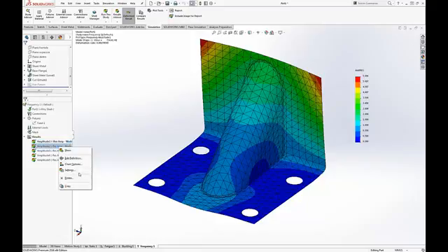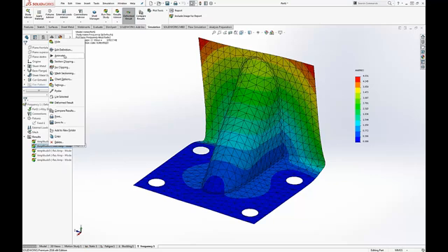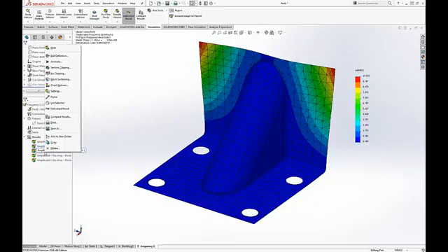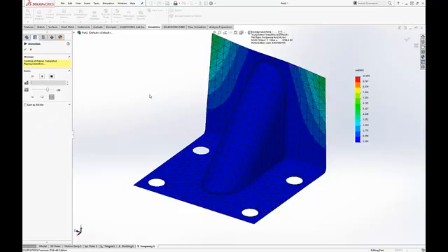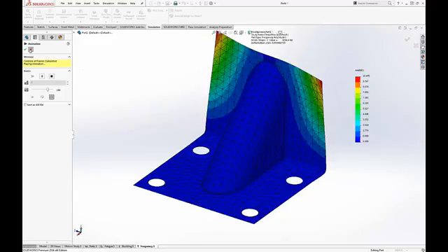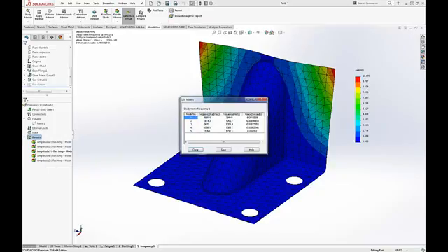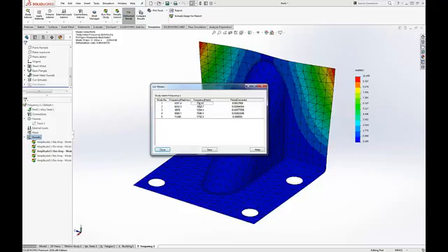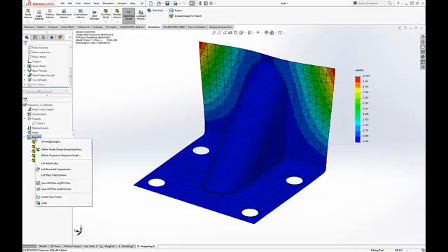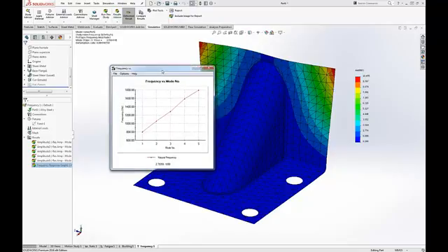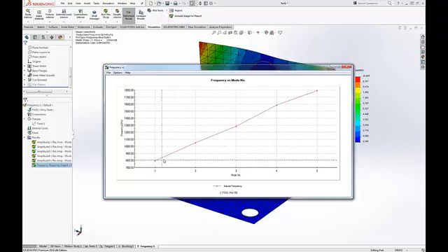Of course, here I can see also other ones. For example, this is the second. Of course, I can expect it to vibrate in another axis, and so on. Of course, I can calculate up to what is needed: 10 frequencies, 100 frequencies, 1000. What do you need? And of course, I can see the results in, for example, resonant frequencies. So this is the first frequency of resonance. Of course, I can see also a frequency response analysis. So these are the 5 frequencies I have calculated here.